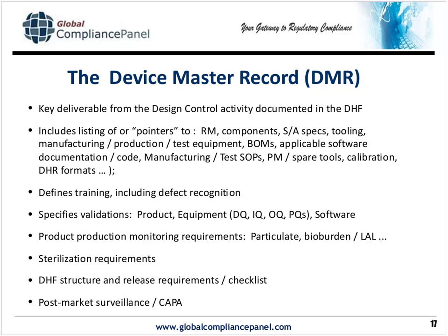But anyway, it is the sum total of all the documentation, either e-documentation or manual documentation, that defines how your product comes to be a product in terms of that lot that's built. So this is the basis for defining your lot records, if you will, and as I mentioned earlier, the device master record, one of its documents would be a template for an unfilled out traveler, an unfilled out bill of material, etc., that is filled out each time that lot goes through, listing the lot numbers, quantities, test results, etc.